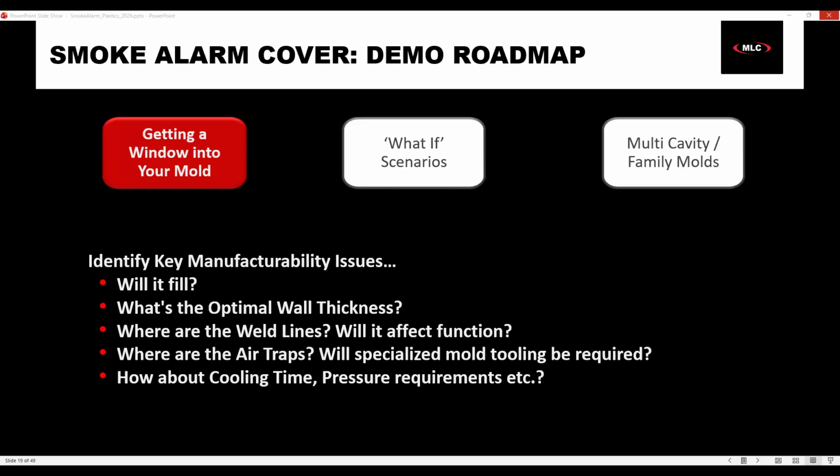So of course, if for some reason you're in that 0.1% where you can't find it, you can always create your own. But again, the amount of plastic materials that are included, I think is absolutely phenomenal with this software. By far the most inclusive. We're going to start working with just a general polycarbonate material. That's what we're selecting for this first run. Again, there are different types of parameters across the top: viscosity, specific volume by temperature, specific heat, thermal conductivity. Those are the base items that we need.